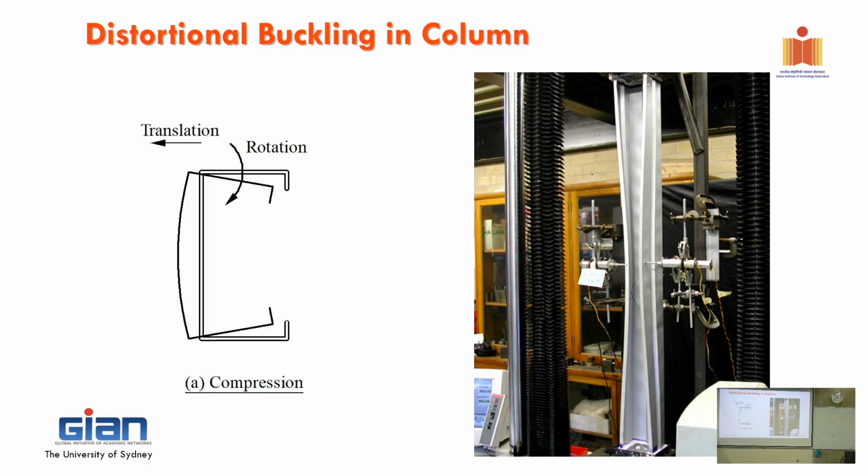You push the flexural torsional buckling up, and this one will come in. But if you don't have that, maybe the flexural torsional buckling will come in smaller, and that one is not going to happen. It's just flexural torsional buckling straight away. So it depends on how you want to do it. But at the end, when you put a knob or whatever, you just calculate three things, and whichever is smallest will govern the design.